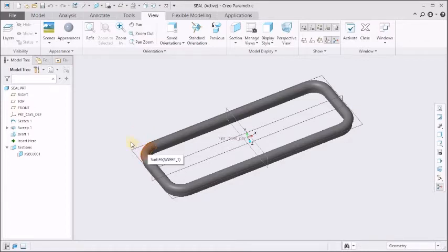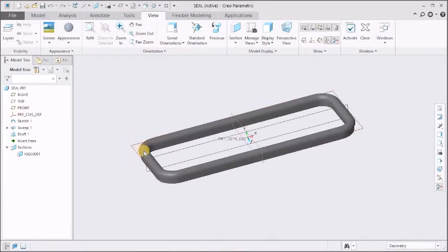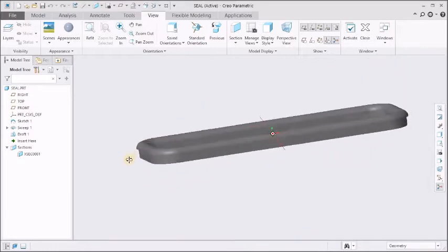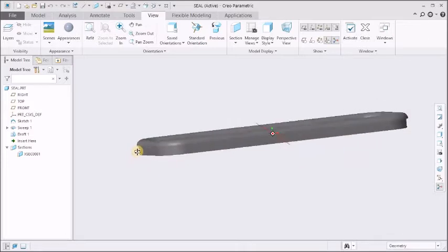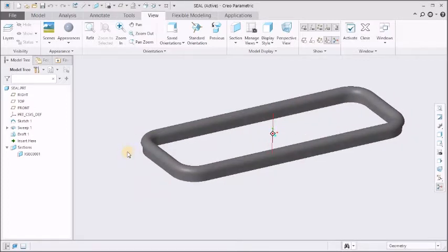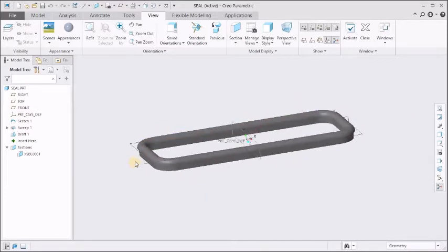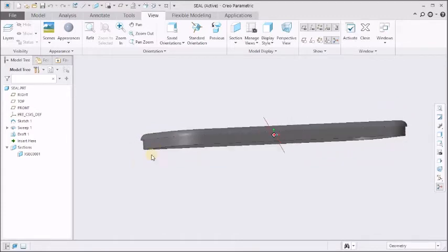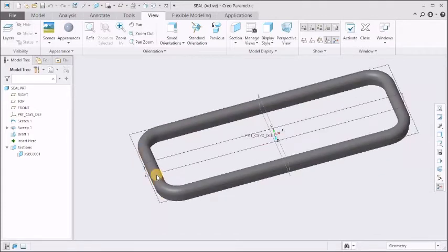Now this is a seal in nitrile rubber. The material of construction is nitrile rubber, and I will be creating a mold for compression molding of this. When we are trying to create a mold, there are certain operations that need to be carried out on the piece. Basically these pieces shrink after being processed for compression molding. So to attain the particular dimensions, we need to add shrinkage to the part feature of the seal